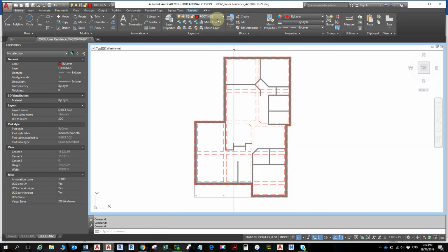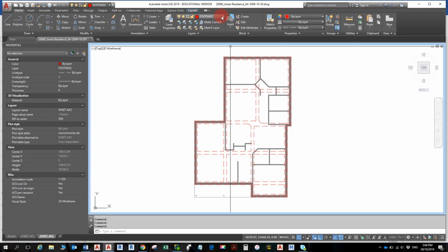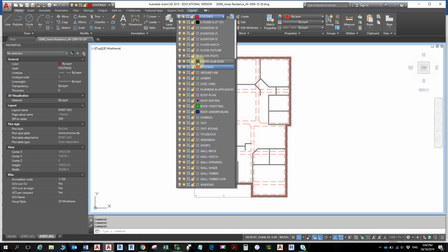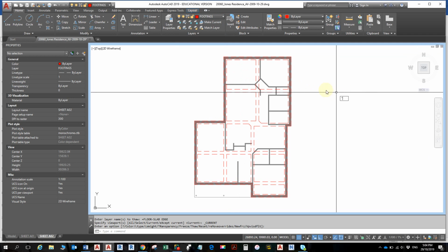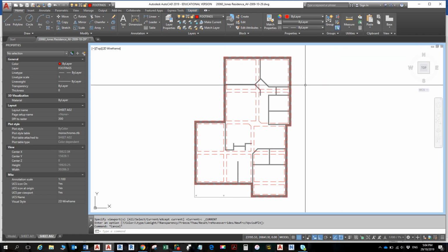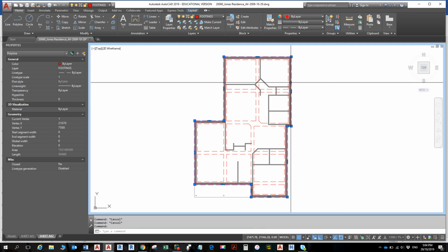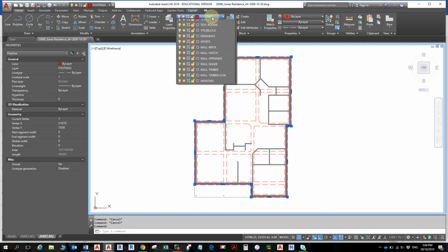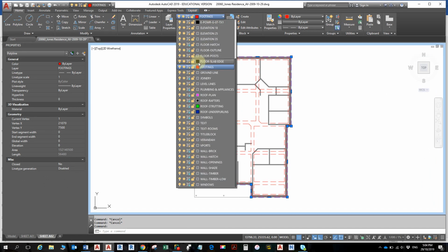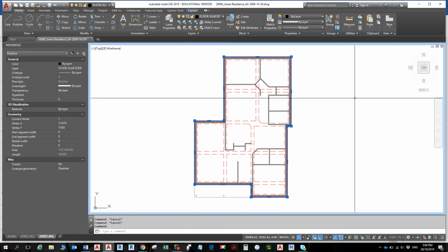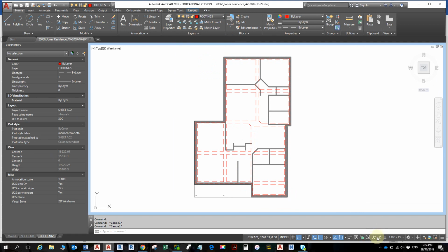Now I've got a viewport in here, so I need to also set floor slab edge to 0.5 line weight. See what that looks like now in preview in a minute. Floor slab edge, drop it in that. We can also just put the line weight button on temporarily just to see what we're getting at. You can see how it's going to stand out really well.